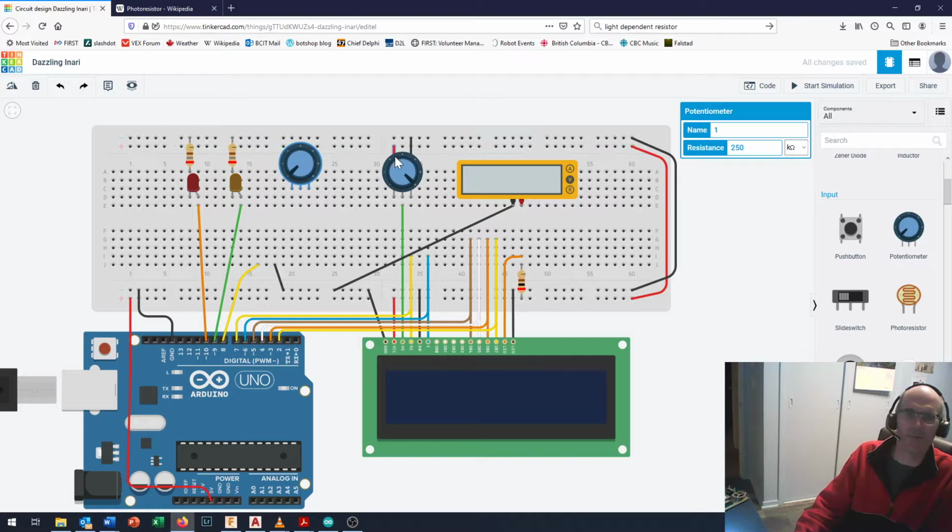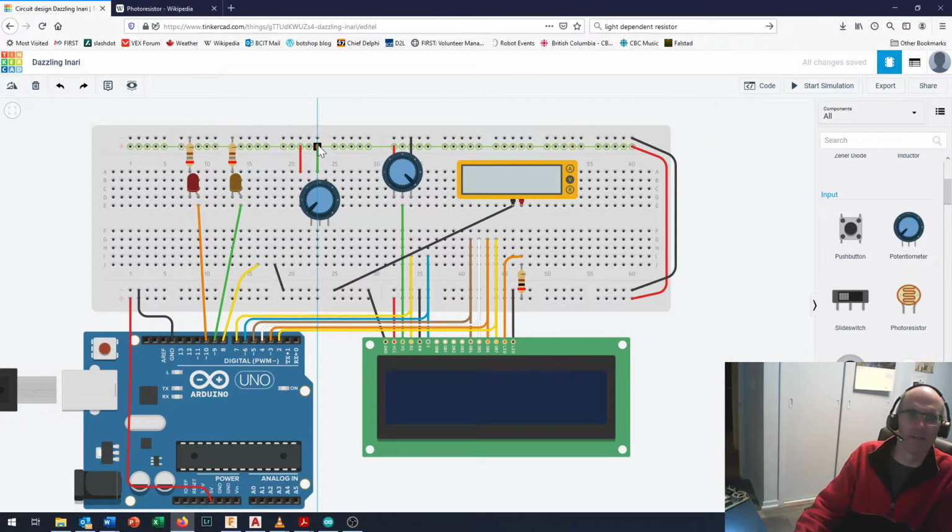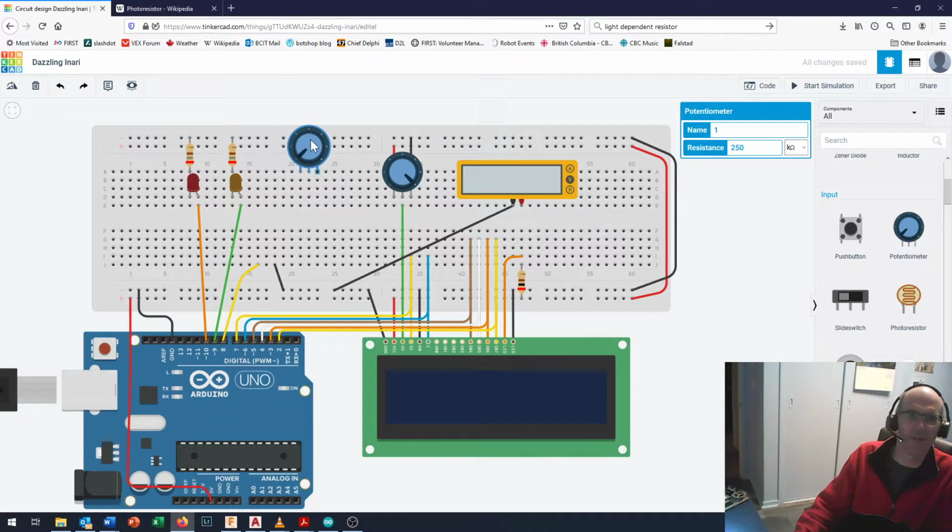Okay, now last time when we used a potentiometer, you can see we tucked a few wires around in the back of it so that we could get red and black coming off the potentiometer. So let's do that again right here. And we're going to set this side into the plus 5-volt line and this side into the ground line. All right, then we bring our potentiometer and hook it up right here so you can see that line is going to be red and that line is going to be black. There we go. We'll just set it right there.